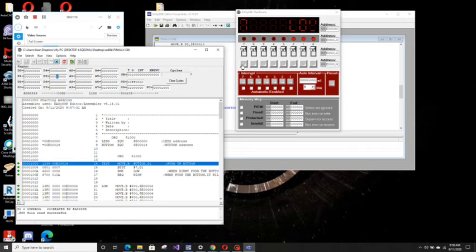And we can see after the countdown reaches 0, it will be repeated again so that new temperature changes will be detected. But if high temperature change is detected, then the count up will begin. This is because the speed of the fan is increasing up to maximum speed, which is 9. And this is to allow the cooling process to occur faster inside the room. And if the high temperature change is maintained, then the count up will repeat again.